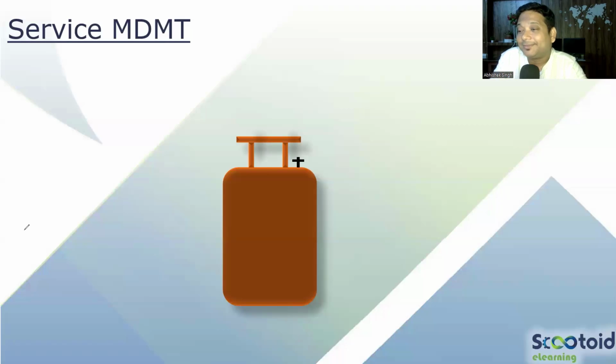And this is the most common reason for having a lower MDMT. Also, the reason for "hold" being written behind MDMT. How many of you have noticed that most of the time in the process data sheet, you will find "hold" after MDMT? Most of the time when you are starting a project, you will find "hold" written all the time when process is giving you the data in the start of the project.